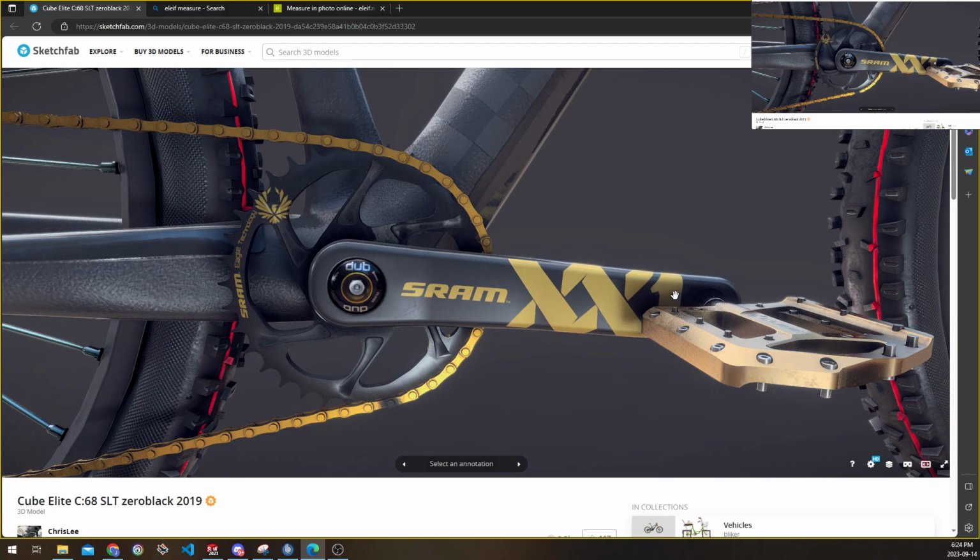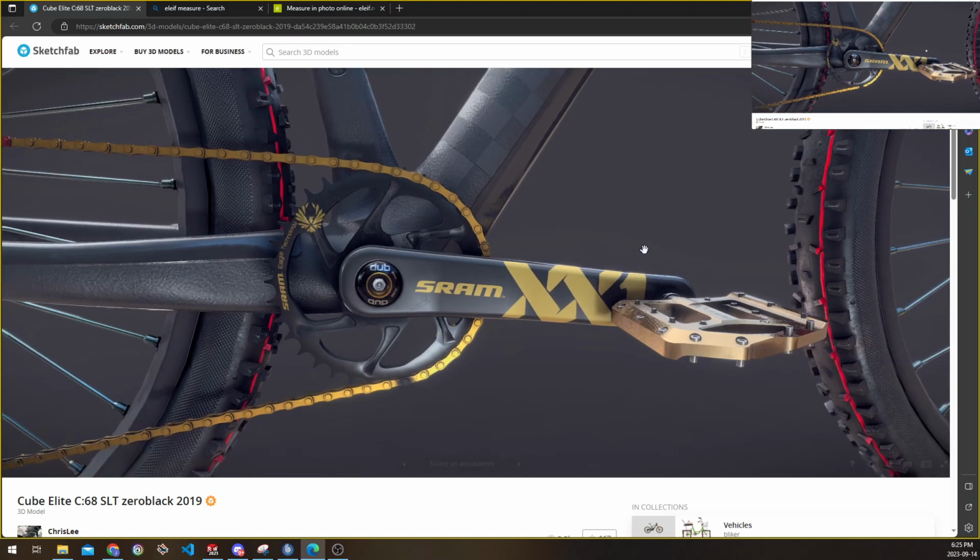If we made the assembly using the shaft part, the origin would likely be the center of that part, and then when we added the pedal, it would have its own origin, the arm would have its own origin, and the assembly itself would have its own origin, if that makes sense. Oh, okay. Every part, every assembly has its own reference origin, and everything else is defined based on that. And that's typically not something you need to worry about too much in assemblies. It's more for parts. Oh, okay, got you. Thank you.